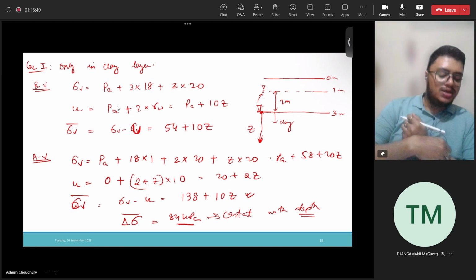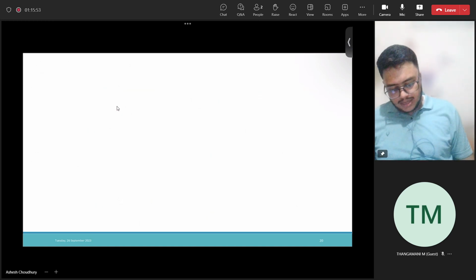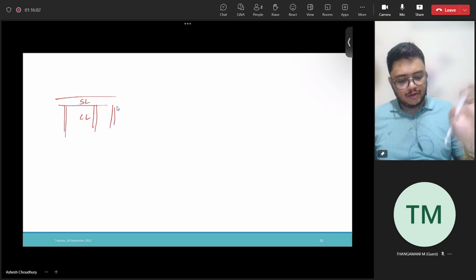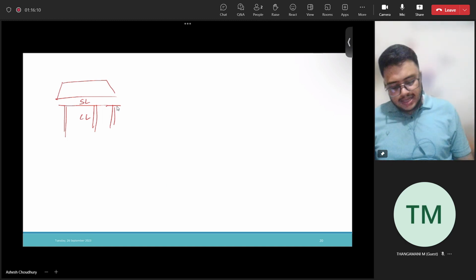Normally, say you have clay and this is the sand layer, and you are providing sand drains, normally sand drains, not applying vacuum pressure. So what we need to do, you need to provide some overburden pressure here in order to develop some effective stress. In that case, what happens?